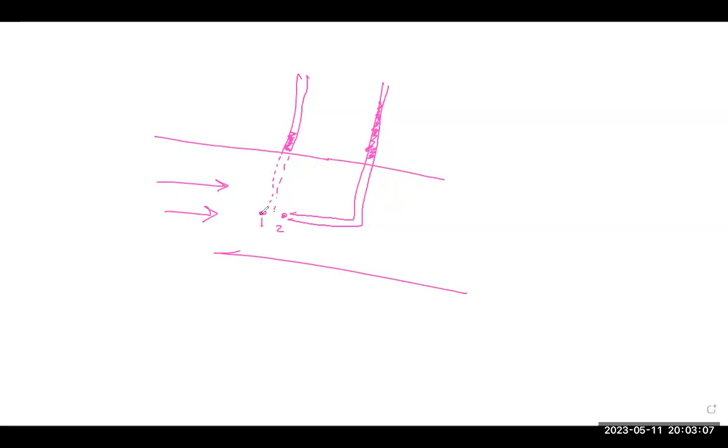Point 1 is clear, it measures static pressure, the same as what I presented to you in the venturi, orifice, whatever. This measures static, no problem. So the first point is static. Or I can say H is static because this is measuring as a head. What about the second tube? What does it measure? For the first point, the flow is not affected, it's still moving. But for the second case, no. Something happened. What happened is stagnation here. You see this?